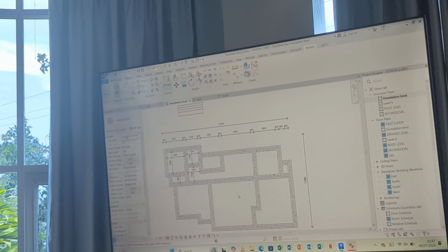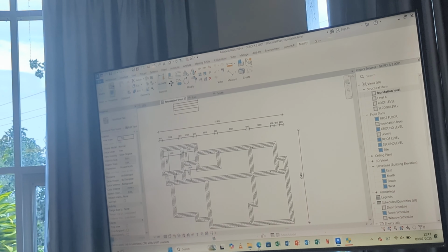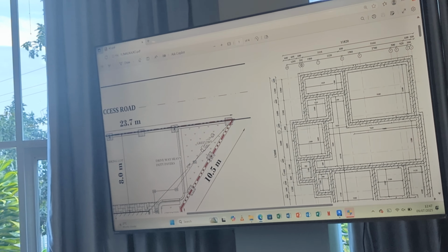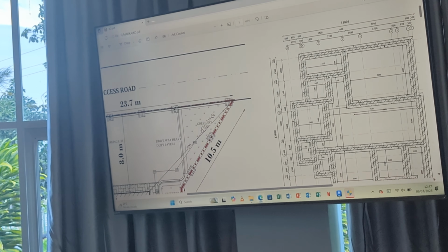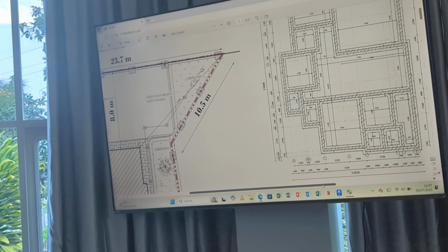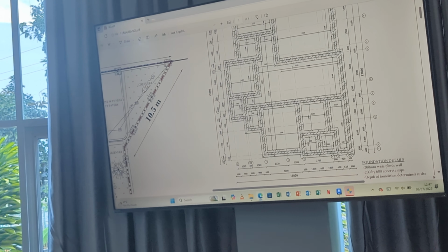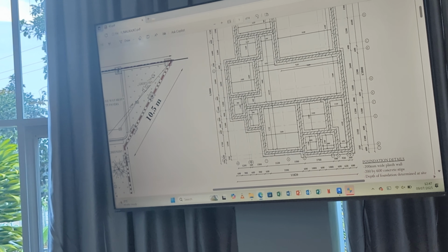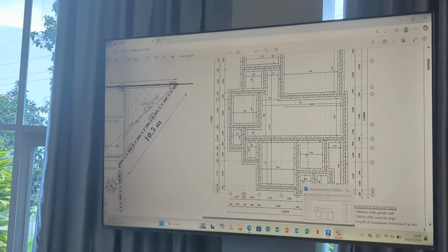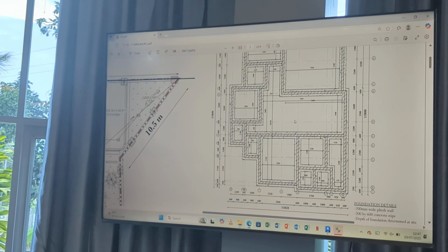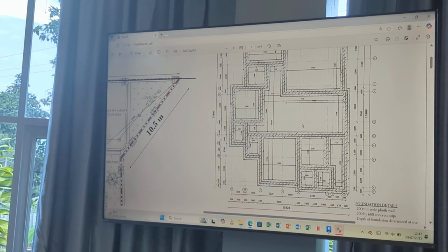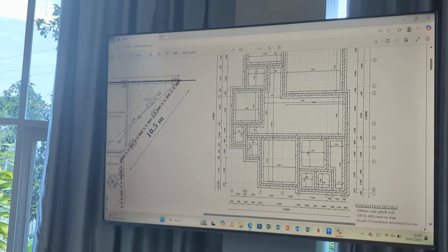Are we good up to that? Yes. Are we not done detailing this? As I said, you do the three exterior and the internal dimensions. That is basically you done with your foundation. Make sure your grid lines are shown, but not dark. Okay, not hidden, but hazy, pale, so they are not dark and crowding your work. Good up to there? Yes.